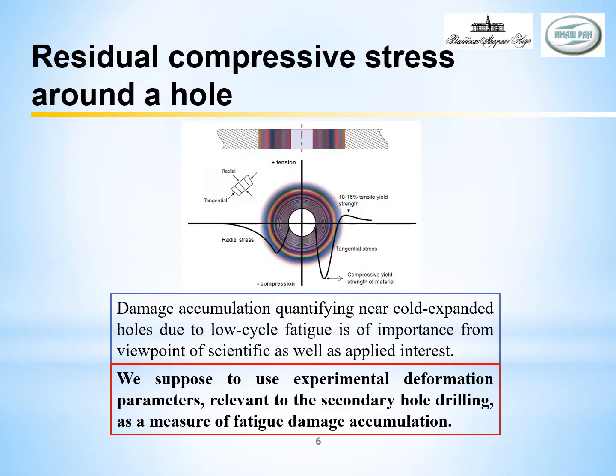Cold expansion of a plane hole induces a zone of residual compressive stress around and through the hole, typically extending radially at least one radius around the hole. Typical applied expansion levels range from 3 to 5% for aluminum alloys.